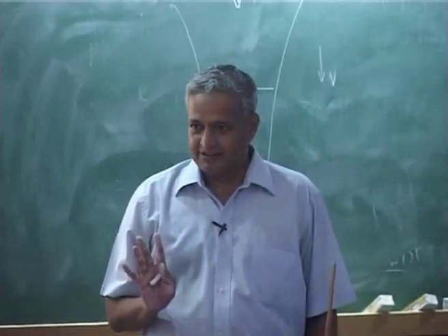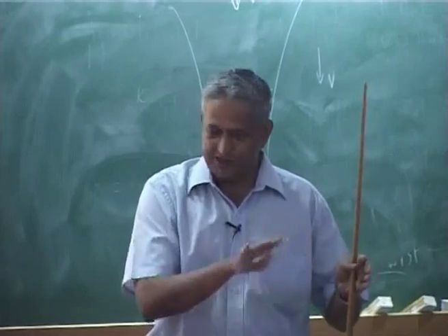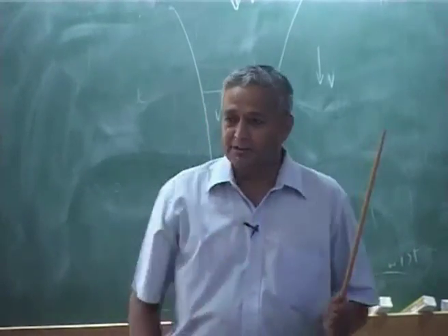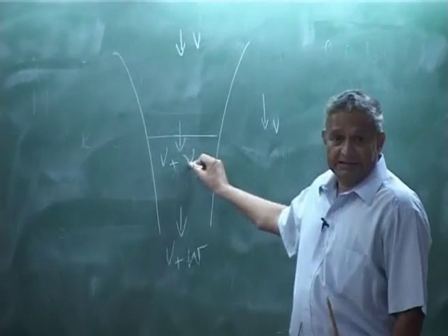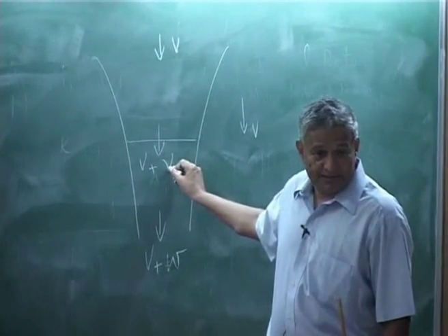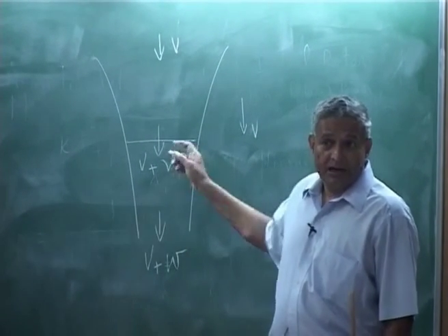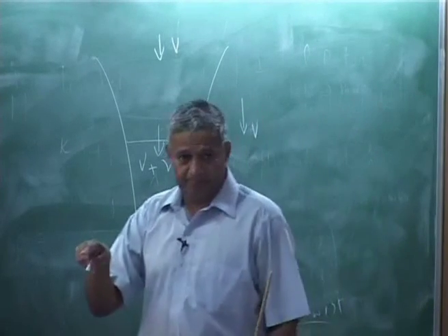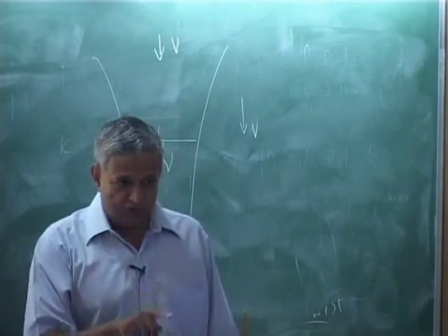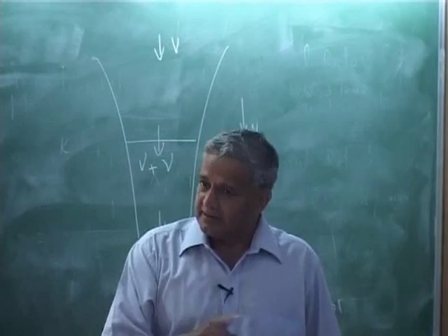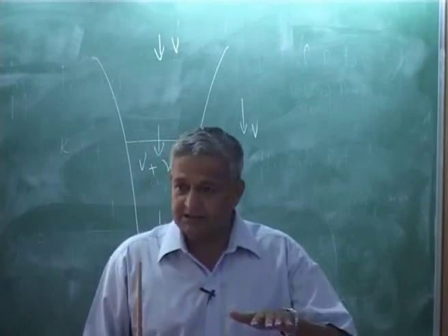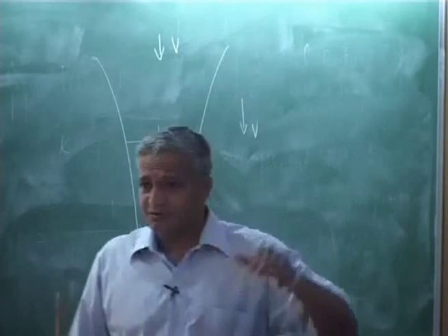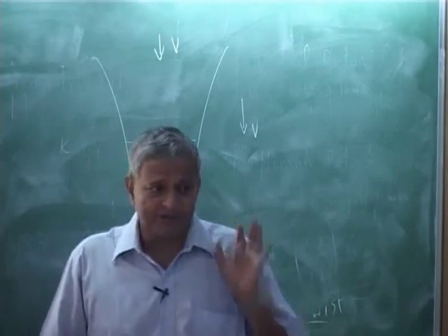Okay. So, this is the first part when you are climbing, but the only thing is the value of nu may vary, because this is not the value at hover. The induced velocity will vary depending on flight condition. In hover, it will be root of Ct over 2 lambda I, that is the hover condition.